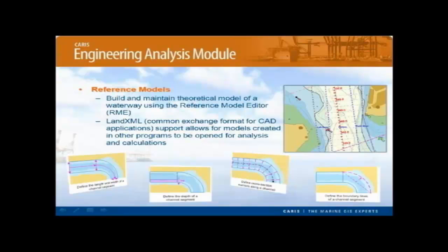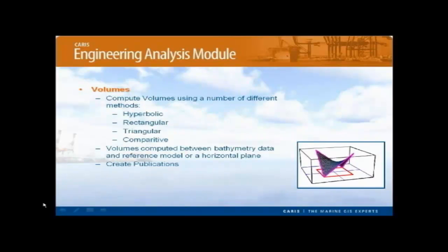So included with the Engineering Analysis module is the CARIS Reference Model Editor, or RME. This allows ports and waterways users to create, build and maintain theoretical models of their channel or waterway. Now another really good feature is that the Reference Model Editor also has support for LandXML, which is a common exchange format for CAD applications. So this means that models that have been created in any other software and saved as a LandXML file are able to be imported into Bathy DataBASE through RME. Which is really going to be useful for a lot of our clients out there. Now, the most important thing that I think this brings to the table is volumes.